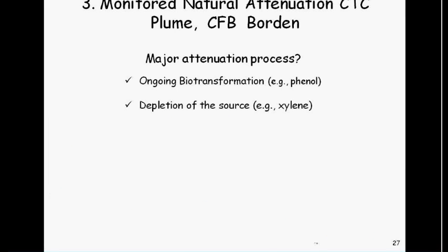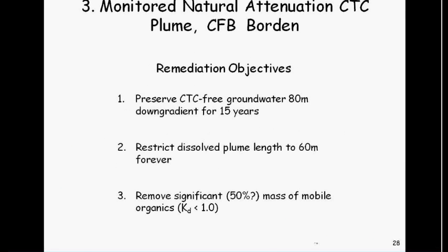So I think that's now my expectation, that at a real coal tar creosote or petroleum hydrocarbon contaminated site, the plume should be shorter than I would calculate, and there should be less mass in that plume than I would estimate by Raoult's law approaches. Doesn't mean it always occurs, it's just now my default.